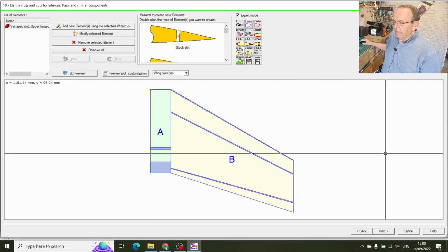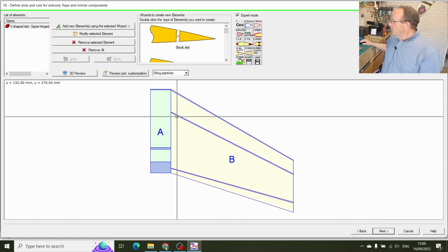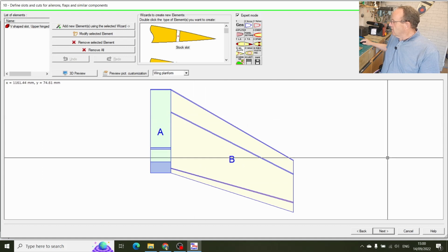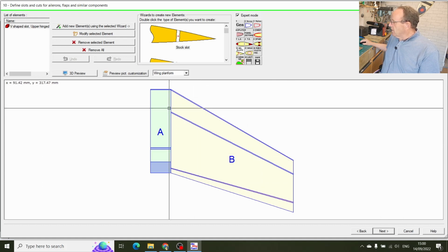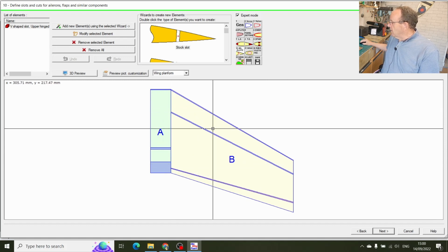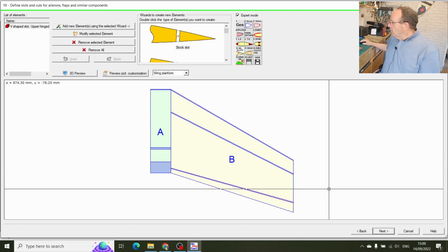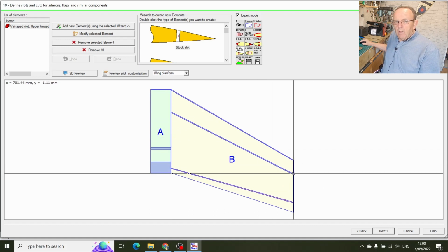Now you could do all this with DevFoam, but you'd have to have a good drawing. And one of the problems you've got to work out when you're doing a tapered wing like this is, if you haven't got the speeds of your wire correct, it will go a lot slower down here and a lot faster up here, and then you end up with it being burnt away at the smaller end. Whereas DevWing Foam takes that into account.